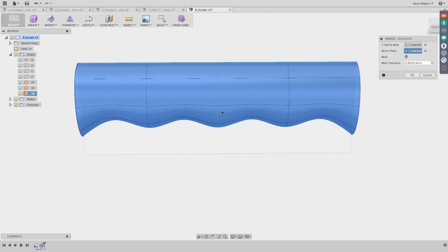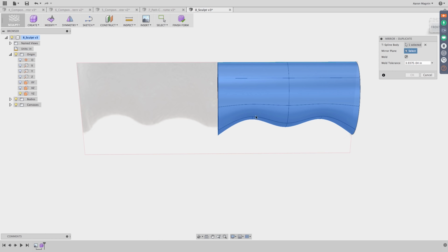And as I did that, this sculpting environment is so smart. It actually recognizes that had I not rounded this off, that curvature continuous nature that we're always after with this design, or often not after with sculpting environment, wouldn't be there. So I'm going to undo that real quick, and I want to show that to you one more time. Right now it's got this really sharp edge, and if I mirrored it over like after I create a body from it, it's not going to look right. It's going to be this really sharp point, and that's not really what we're looking to achieve in this case.